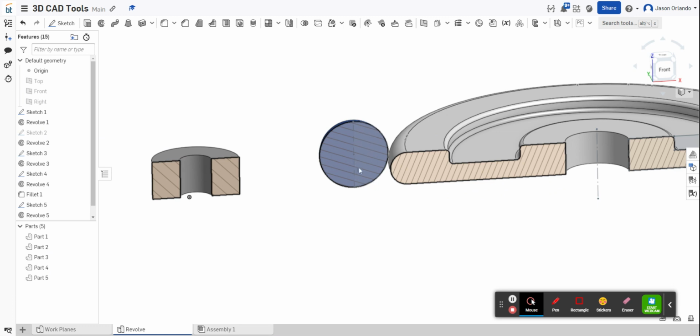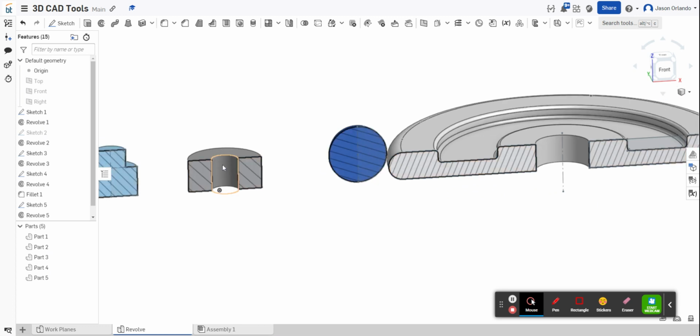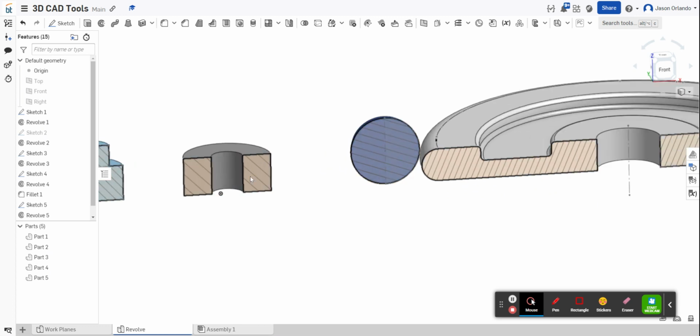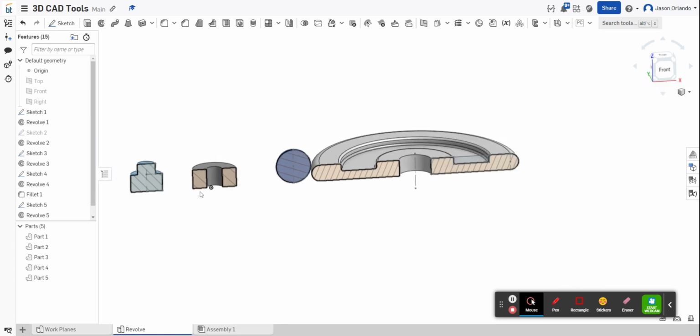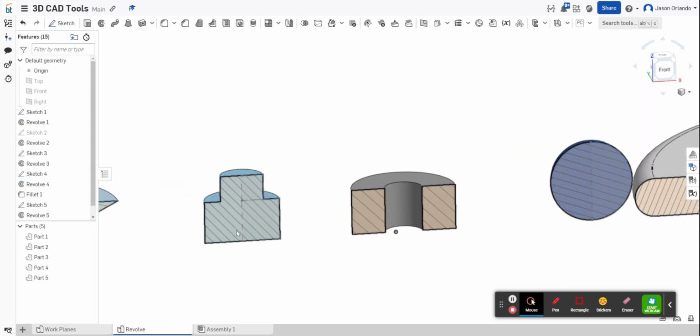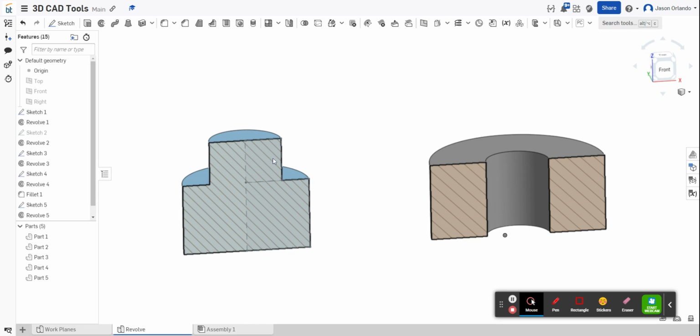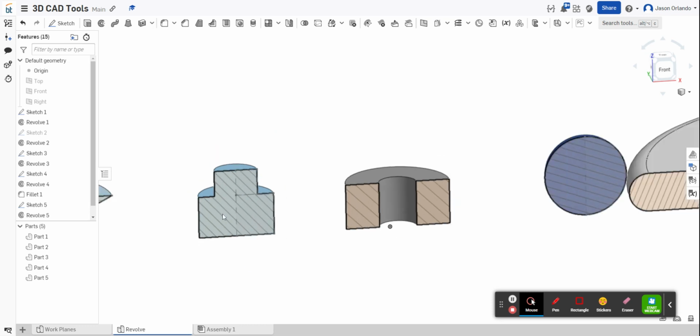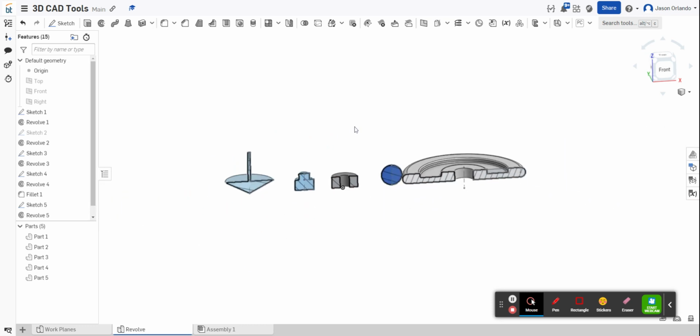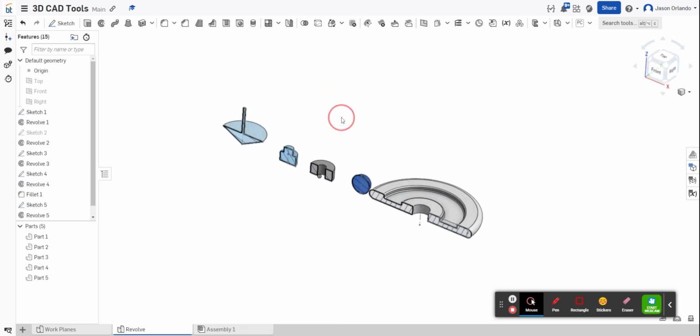When I did the sphere, I only sketched the semicircle. When I got this little washer or donut, I sketched one rectangle, not two. When I sketched this, I had one rectangle and another one that had left edges that were aligned. And then I got this symmetrical side here through the revolve. Okay. So there you go. That is the Revolve tool.